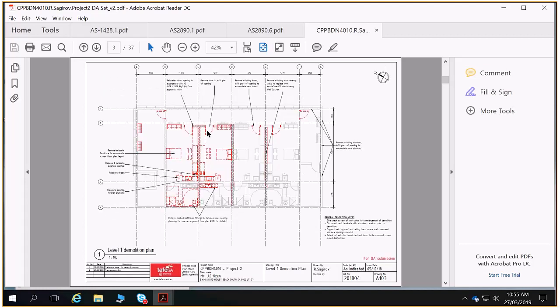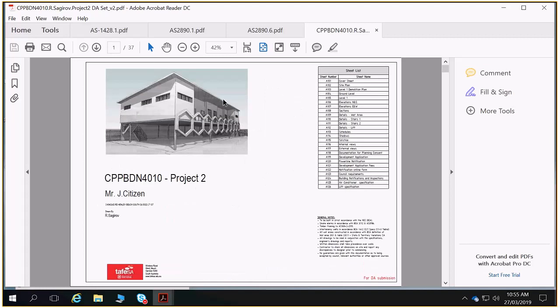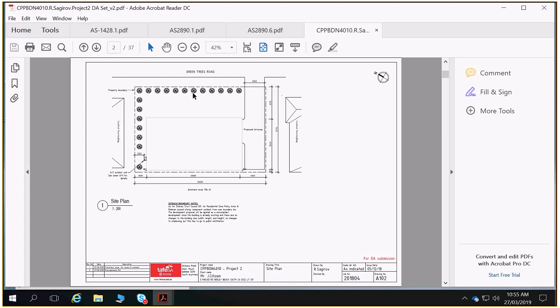One other thing I'd like to bring up is in regards to structure in general. So we have on that building this skillion roof. Now, if you look at that from the Revit model in its elevations, that is an incredibly thin roof for spanning those distances, etc. Just assume that there are trusses, etc., that are able to achieve that, and we've got some sort of steel structure in there that's enabling that.